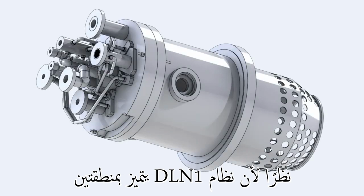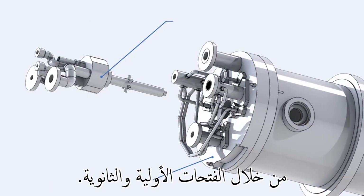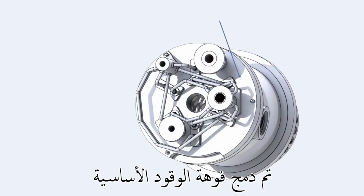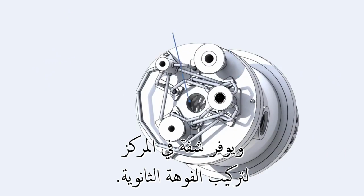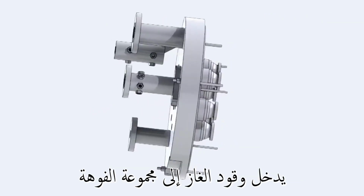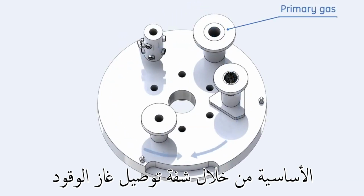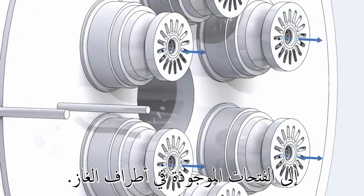As the DLN-1 system features 2 combustion zones, fuel is injected into the combustion chambers through the primary and the secondary nozzles. The primary fuel nozzle is functionally integrated with the combustion chamber end cover and provides a flange in the center for secondary nozzle mounting. Fuel is injected into the liner primary zone through 6 identical nozzles. Gas fuel enters the primary nozzle assembly through the fuel gas connection flange and is routed through internal machined passages to the orifices located in the gas tips.